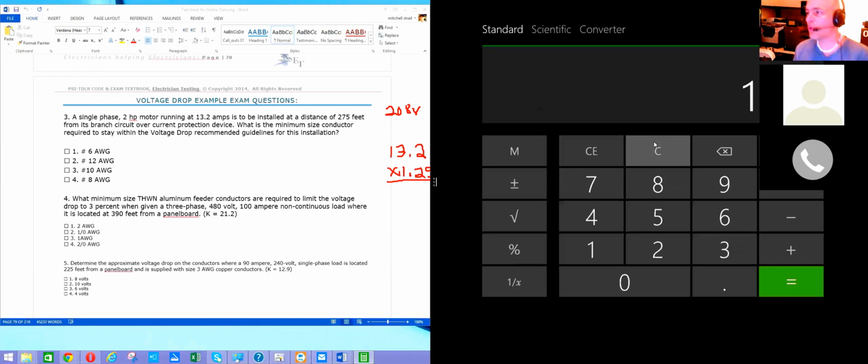Now, I didn't do it on that first example because I didn't want to overload you with too much, so that's why I left it at 13.2. But you have to remember, if there is any indication that it's commercial lighting of any kind, whether outside, building lighting or signage, or any kind of commercial occupancy that might have to do with lighting, that's always going to be continuous duty. Even if they told you it wasn't, it would be almost impossible to argue that it wouldn't still be continuous duty, because there's no way you would consider a commercial building to be open for 3 hours of business or longer at some point in its career.